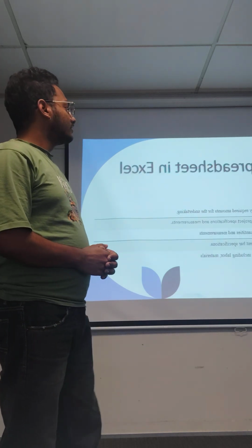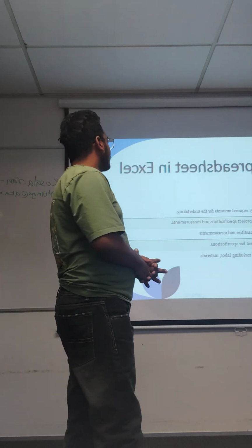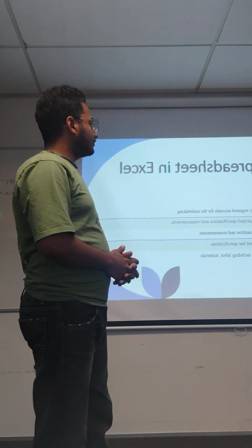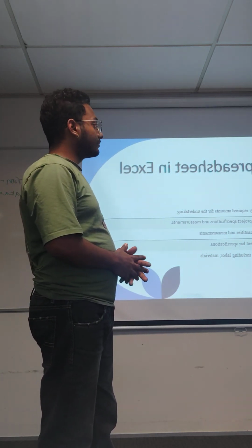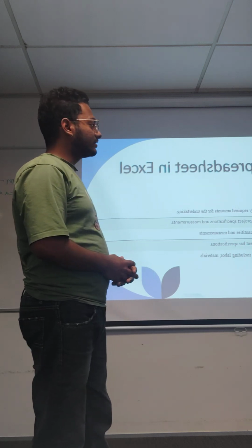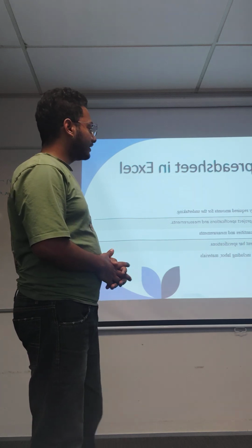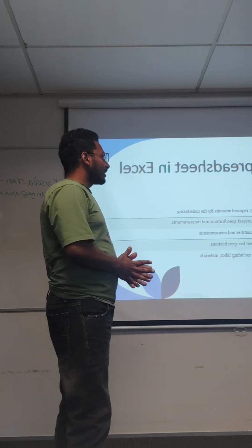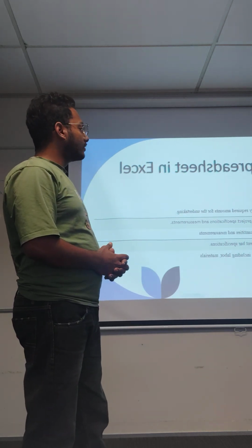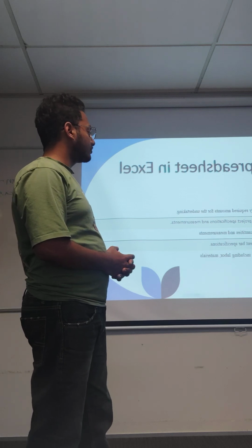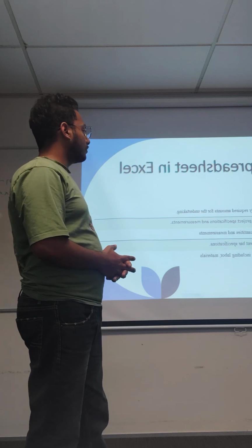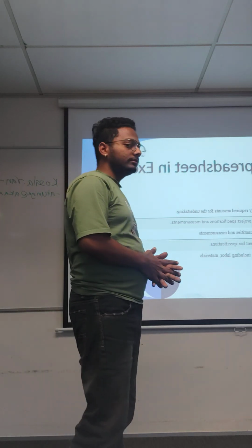Next slide. Firstly, setting up a spreadsheet in Excel. In the spreadsheet, SOQ, schedule of quantities, records the generally required amount for the undertaking. Next is TDS, tender data sheet, containing detailed project specification and measurements. Third is the abstract, which summarizes the quantities and measurements. Bar schedule details reinforcement bar specification. Rate build-up breaks down cost, including labor, material, and overhead. Next slide.